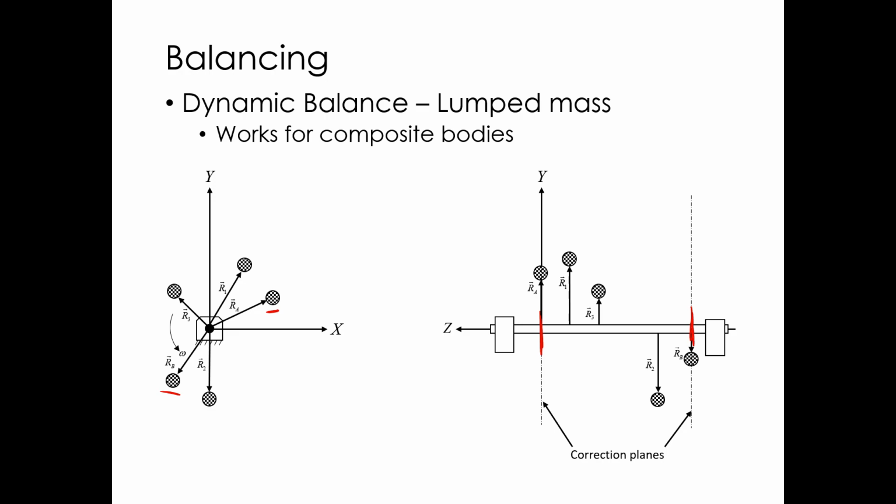Now theoretically you can put them very, very close to each other and balance it. You can't put them on top of each other, and you can put them wherever you want along the z-axis, but in general you want them to bracket the CG of the things you're trying to balance. So all of our CGs, the thing we're trying to balance, are here. So we really want to bracket those with our planes. So we could put our planes here, and that would make sense.